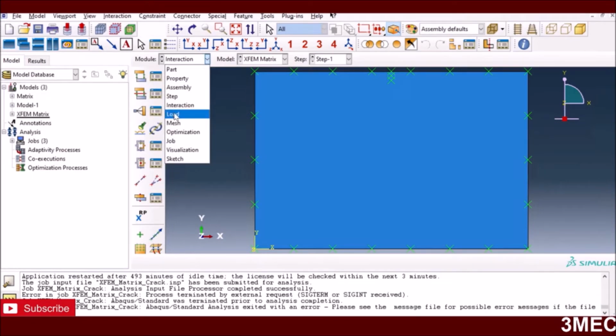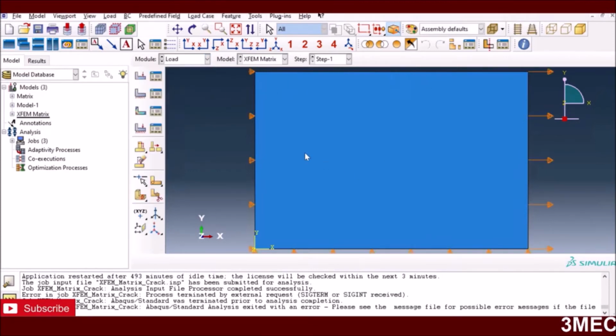All right, and what else, if I'm not forgetting anything? Yeah, so then I have used the same boundary conditions that they did. So I have fixed it from the left hand side, and I'm pulling from this side with some displacement boundary conditions, and I am also fixing the bottom part. In their case, it was not clear to me if they had fixed it or not, but for normal tension type tests, I believe it should have been fixed in the vertical direction. Otherwise you can just fix this corner as well if it was not.